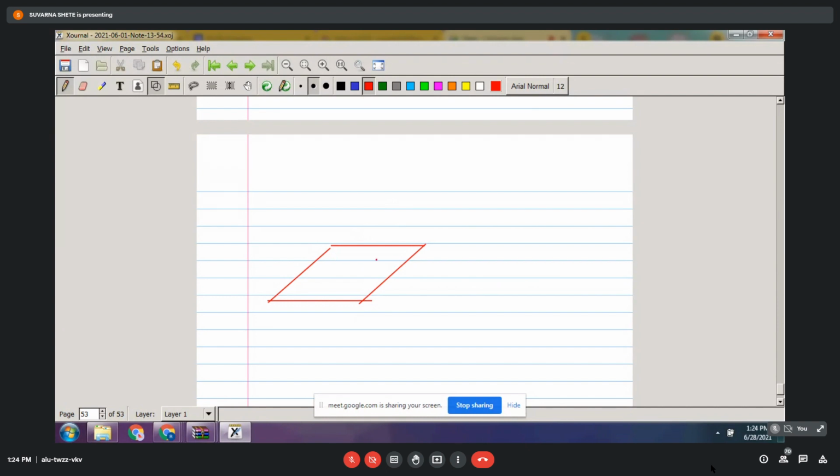If suppose this is a kind of raft foundation, there is one type. So you consider that raft foundation is one of the types of footing or foundation in civil engineering, where soil strata is very weak and its safe bearing capacity is very less. In that case, such kind of raft foundation is used. So what is raft foundation? From this entire base, some vertical columns are constructed and they are having their connection entirely through this flat slab.